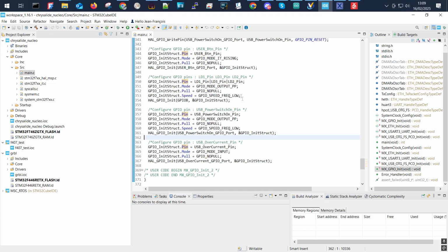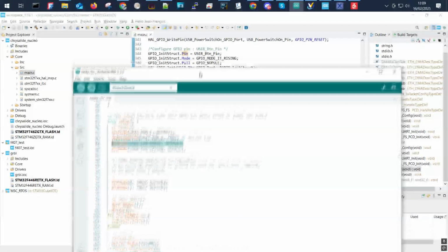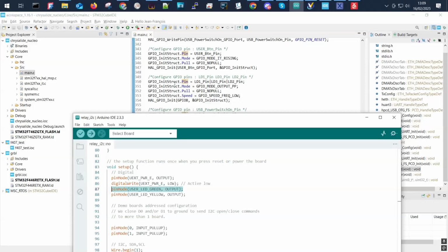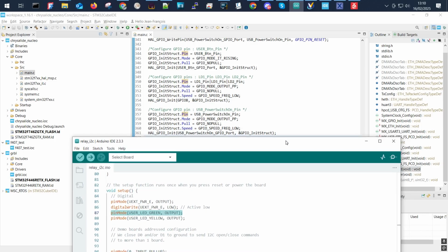to program facilities. When we are using this IDE and we see the powerful capability of the microcontroller, we can tune the rising edge of the output, for example. We can have a fast input-output, or we can slow them down if we have some issues with the electronic hardware, or if our program is too sensitive to electromagnetic pollutions.